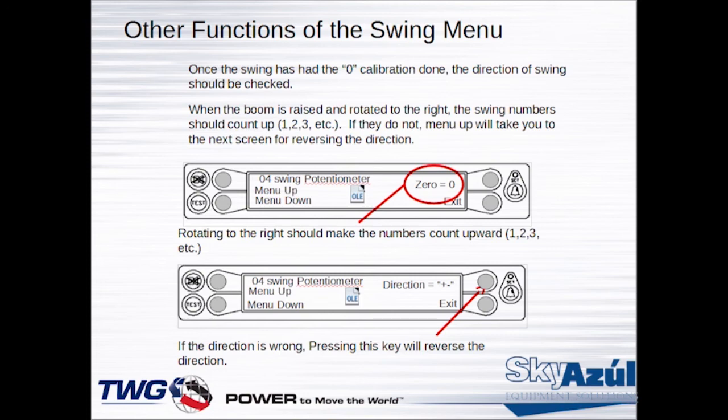One time I was up working at Terex doing some calibrations, and we kept getting these sloppy calibration results, and come to find out their level was off 2 degrees. So it was really throwing a kink in the radius. So this is really important when you get done with these calibrations, that you get that tape measure out and throw it on there. It just takes a few minutes to run through a few of these steps and record them. Get a piece of paper and record what your display says and what your tape measure says, and then you can put a plan of action together to fix whatever the problem is with the calibration. If you don't do it that way, the bad problems only get worse. The way to correct it is measuring things. Any questions on that? All right.